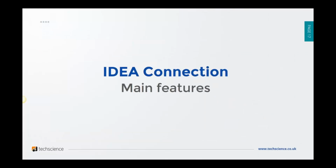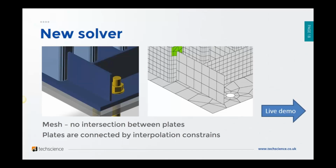So what are the main features of IDEA Connection? First of all, we have introduced a new solver. And you probably know that when you are working in general finite element software and you want to connect two plates, you have to solve the intersection between these two elements. And the mesh in that area is usually deformed and with higher density because of the intersection. If more plates, of course, intersect close to one point, then the situation gets even worse.